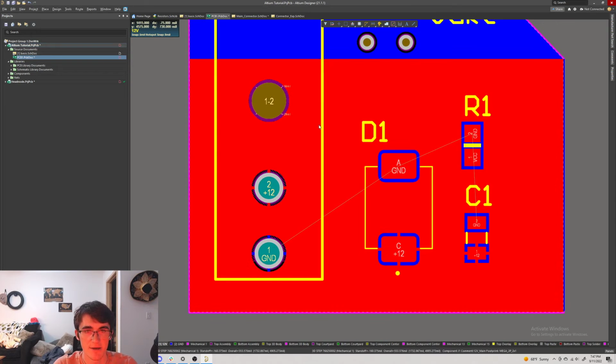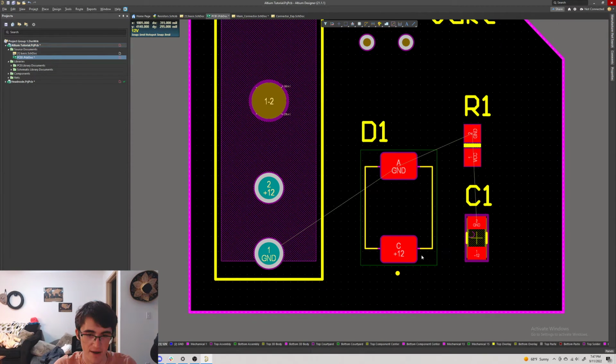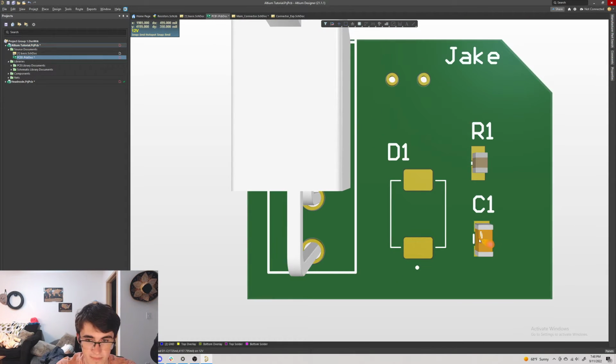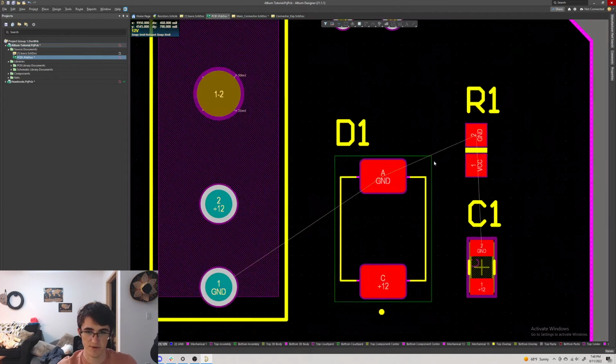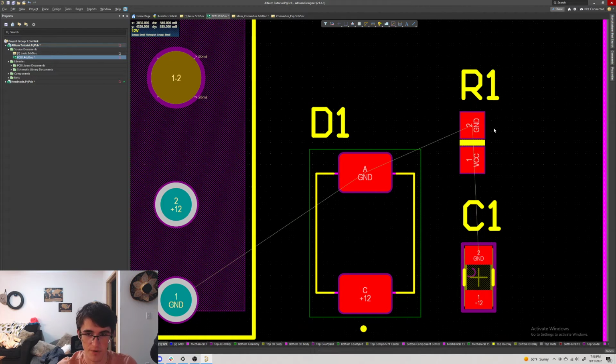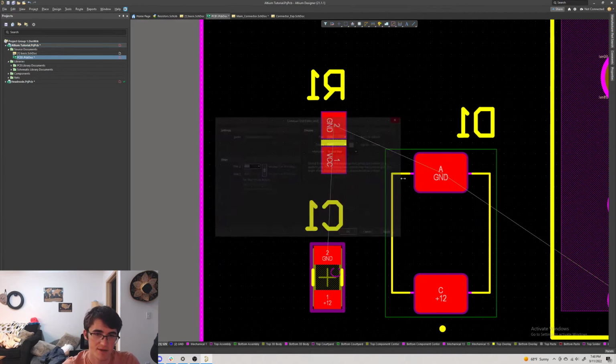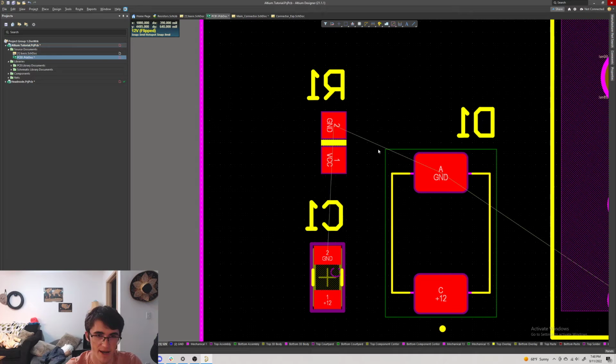It's kind of nice. Just to show how you can do Control W, you want to select on this pad here, because this is the conductive part from the copper in the board that's going to go on the surface mount part. On the resistor here, this is the actual resistor. These gray tabs here will be soldered onto the pads from the PCB footprint, which will then connect to, and you can see that probably better on the back.